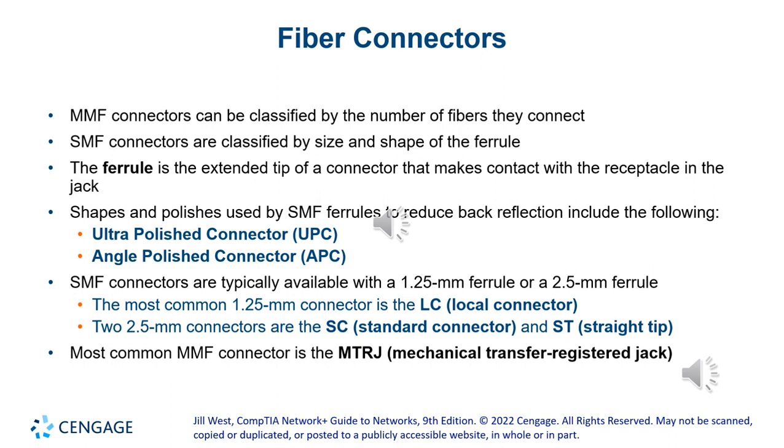They come in different finishes: an ultra polished connector or an angle polished connector, which is cut at an angle. That depends on the manufacturer, how the patch panel is made, how the devices are made. In the old days, every time you terminated a fiber and put a connector on, it had to be polished by hand, and there was equipment to do that. There was a microscope where you could shoot a light and look at the termination to make sure it was polished correctly.